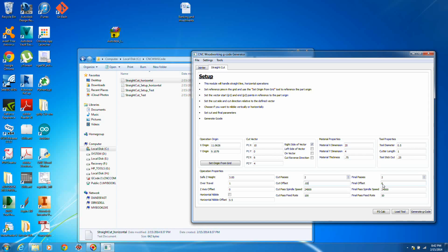And in the same way, you could install a tongue and groove kind of slot cutter in there, and you could set your axis halfway up. If you could zero it out right, and then you could do the math and figure out where it needed to be right in the middle. But let's say 0.375, that's halfway up. Now you're going to be cutting a slot into the material. Actually, let's see here. We would want to probably go from 0 to, let's say, make it a 1/4 inch deep.